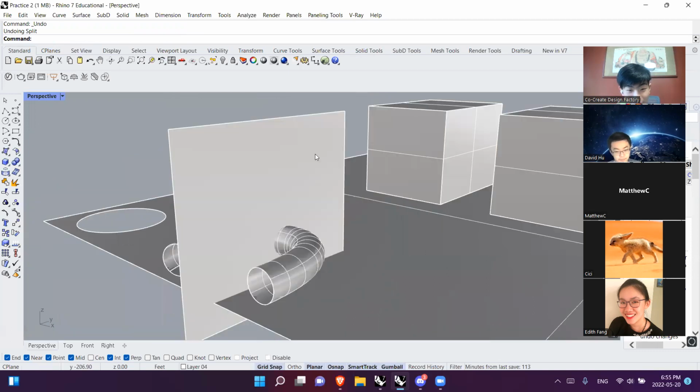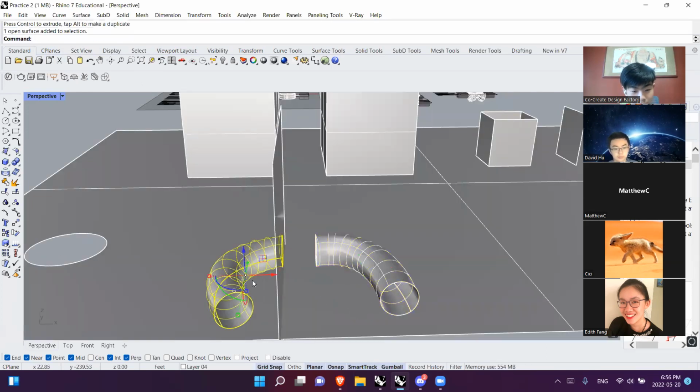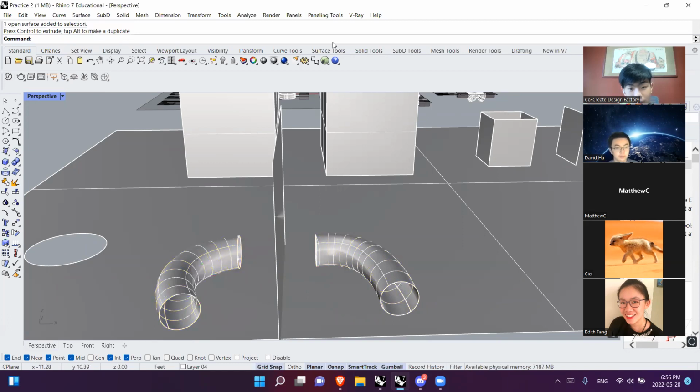But if we want to do it the right way, which means cutting the tunnel in half, we have to select the tunnel to be the object that's split. Enter. Cutting objects, always the knife. Enter. Now you can see that one surface split into 2 pieces. So we have one piece of our tunnel, and another piece. So that's splitting things.